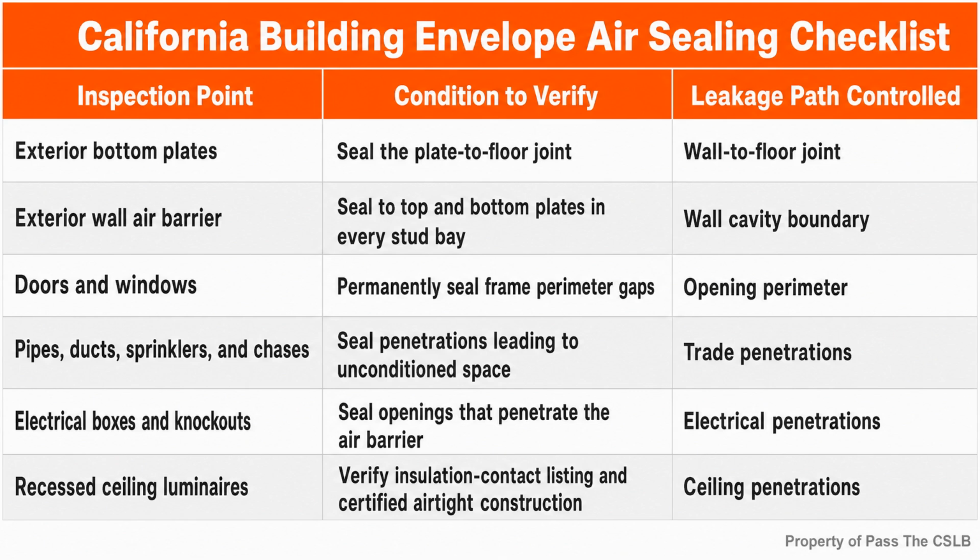During depressurization, air outside the enclosure moves inward through available paths. A person may feel concentrated air movement near a plate joint, window edge, electrical opening, or another missed penetration. The test gathers the combined effect of leakage across the enclosure, rather than judging one crack in isolation. The fan reading is not a contest over how much air the fan can move. The equipment is used to determine how much airflow is required to maintain the standard pressure difference. That relationship allows the rater to report a standardized enclosure leakage result.